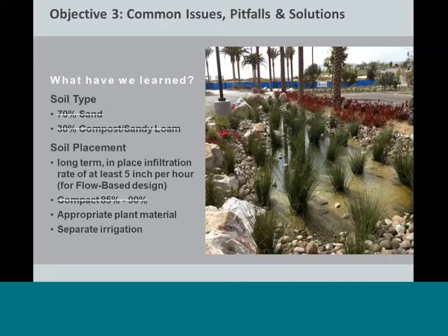Compaction was also a key element. We saw a little bit of variability there, but a lot of specifications were looking for a compaction rate. Civil engineers and contractors are used to asking what the level of compaction is when doing earthwork. We saw 85% compaction, we saw 90% compaction, and that was a big question. What should it be? Or should we even be specifying a level of compaction? Is that important, or are there other design goals that we should be focused on?